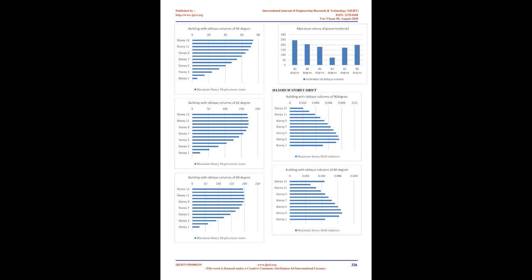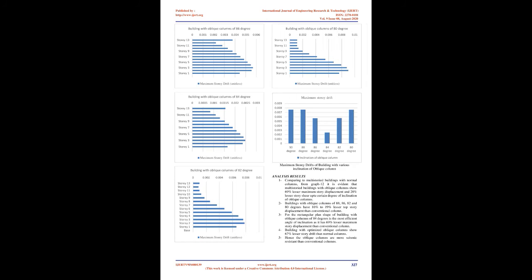The codal provisions as per IS 1893, Part 1-2002 Code for Response Spectrum Analysis of Multi-Story Building are also summarized. Response spectra. Response spectra are curves plotted between the maximum response of an SDOF system subjected to specified earthquake ground motion and its time period, or frequency. Response spectra are often interpreted as the locus of maximum response of an SDOF system for a given damping ratio. Response spectra thus help in obtaining the peak structural responses under linear range, which might be used for obtaining lateral forces developed in a structure due to earthquake, and thus facilitate the earthquake-resistant design of structures.